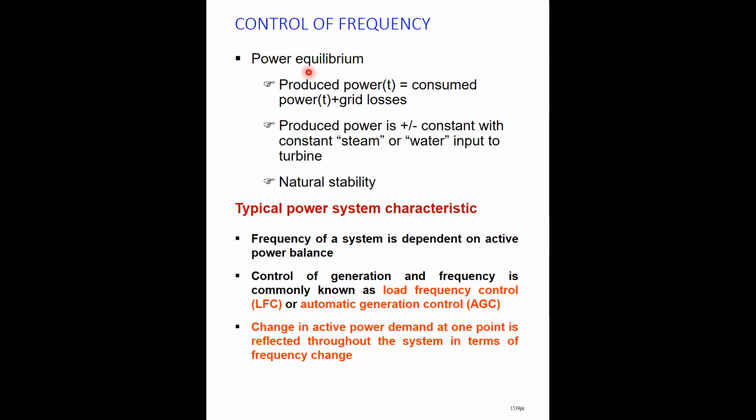Whatever power is produced has to be consumed by your load, and also because you supply power through your network to the consumer, whatever power is generated should be equal to the power consumed, plus some amount of power loss that takes place through your transmission or distribution.